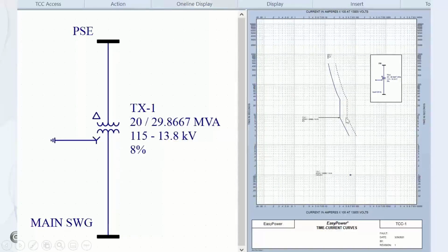The jog in the curve is meant to indicate the frequent fault versus 100% withstand. And again, in those standards that I referred to earlier, they define the frequent fault terminology, the size of transformers, and the number of faults that a transformer of that size can absorb. So when at all possible, you want to avoid excursions into this area, but the curve tells us that the transformer would survive some limited number of faults that exceed this particular value, as long as it doesn't exceed the max value.